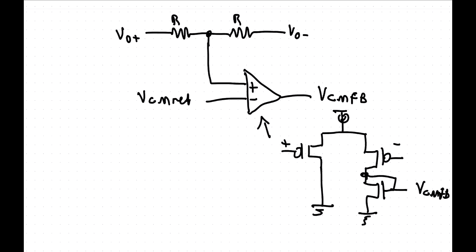So the amount it changes from natural point is that change divided by the feedback loop. Now it doesn't actually matter so much if the common mode wobbles around a little bit. That's not critical. What you want to make sure is it kind of sits round about the target, which is probably half your power supply. Well, it should sit around there. If it wobbles up and down a little bit, it's not actually very important.